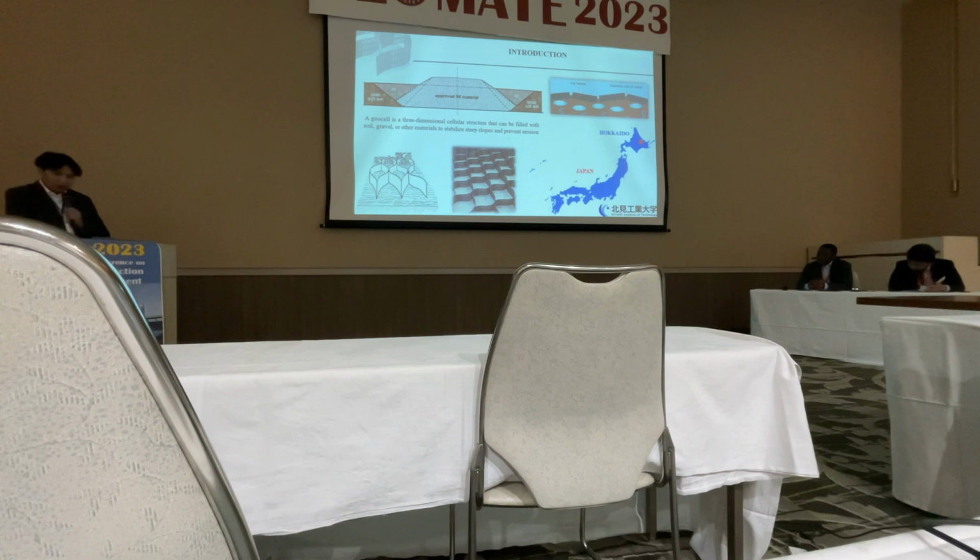For this reason, we tried to strengthen the road subbase by using geocell instead of the traditional soil replacement method. The method of strengthening the subbase using geocell increases the bearing capacity, suppresses uneven settlement, and disperses the pressure from above. In this study, we obtained results by observing the freezing, thawing, and loading periods of an actual test road reinforced with geocell.